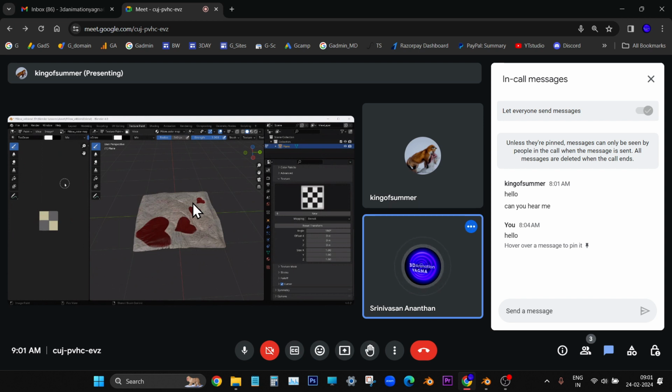Yeah, save as. Now it will ask for a 16-bit. Press 16-bit PNG, and wherever you want to save it. And under the 16-bit, compression should be 0 always. Always whatever you are saving as PNG, it should be 16-bit, and compression should be 0.